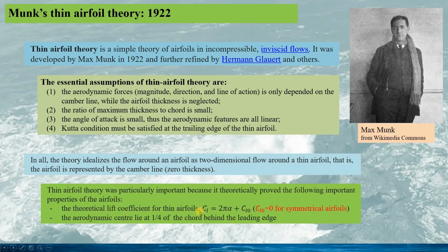For instance, the theoretical lift coefficient for a thin airfoil would be given by this formula. Here, CL0 would be 0 for symmetrical airfoils. And it is proved the aerodynamic center lies at the quarter of the chord behind the leading edge.